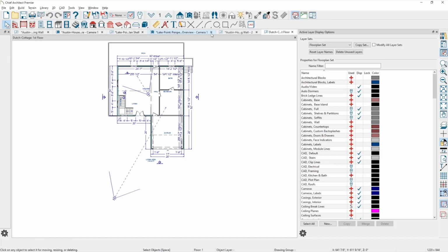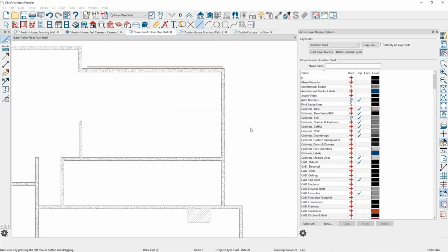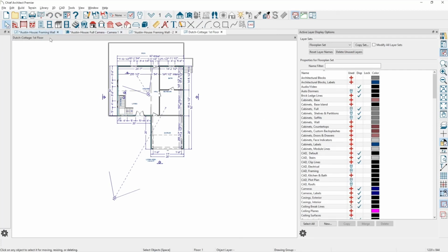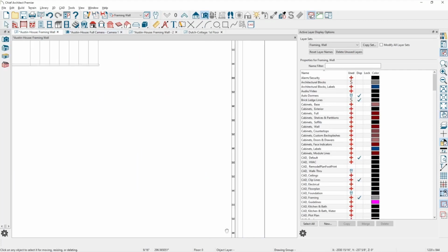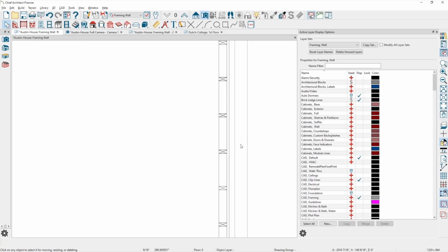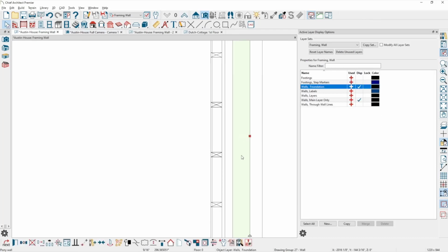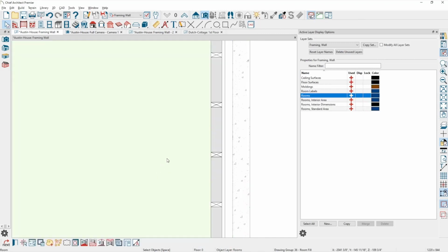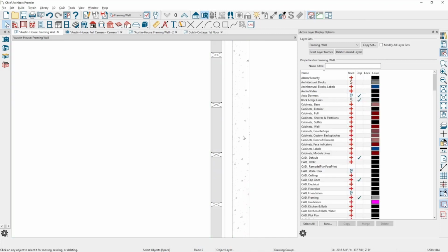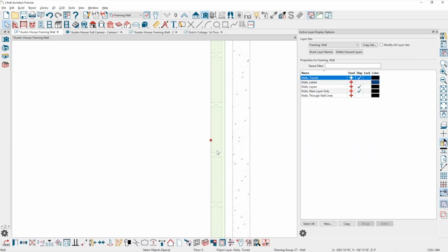All right, so your first question about how close can the wall get, let's go into the plan that we were kind of working on. In this case, if we zoom real close in, I've got 2 walls here, right? Let's turn on our layers so we can see the level of detail. This is a 6-inch concrete wall with a lower ledge that has an 8-inch, and then this is a furred wall out here.